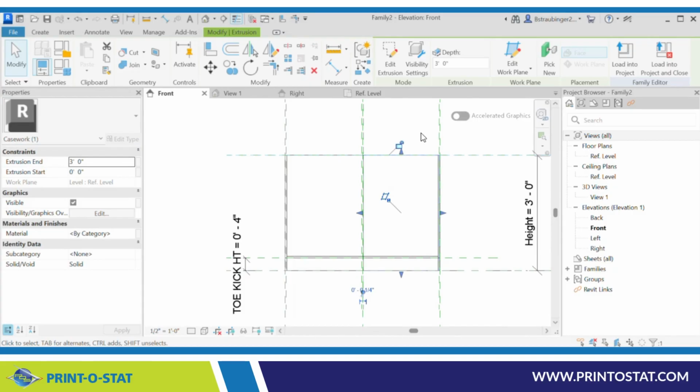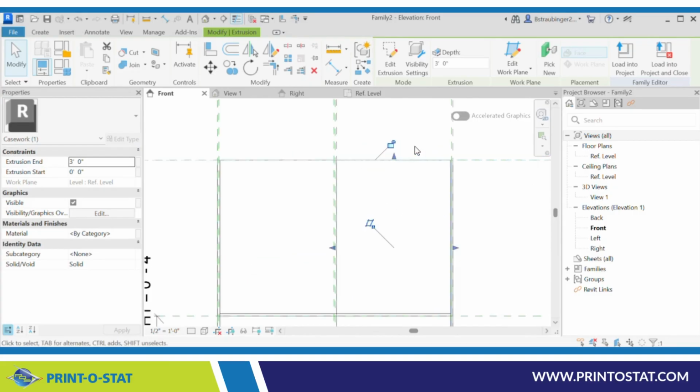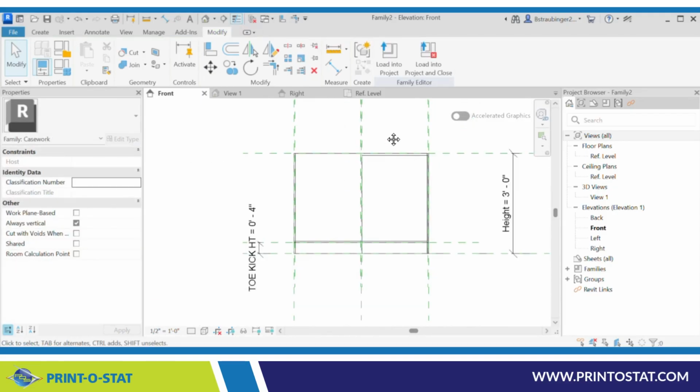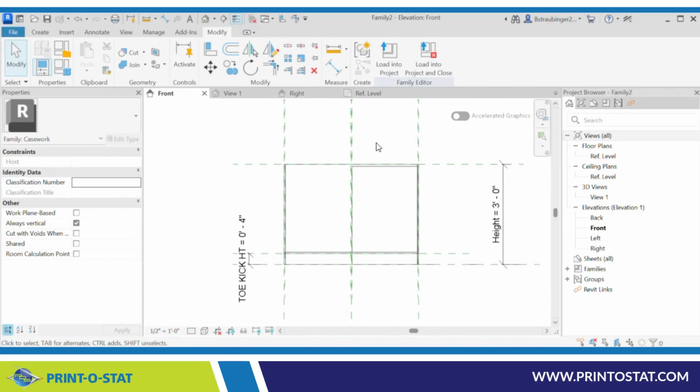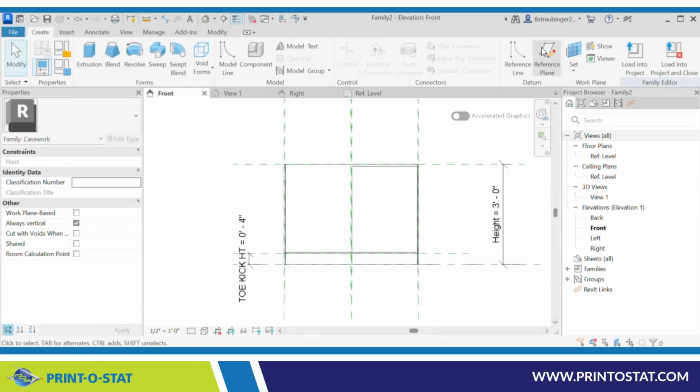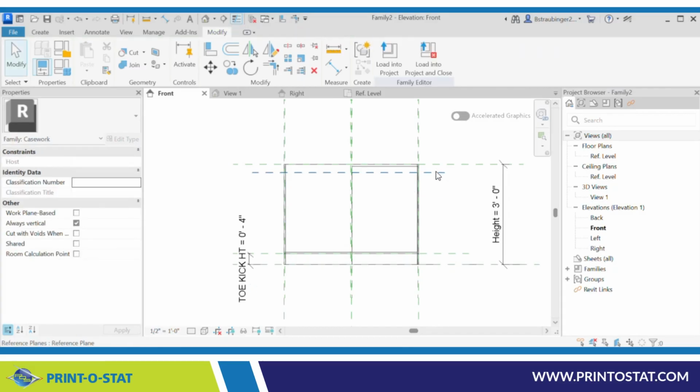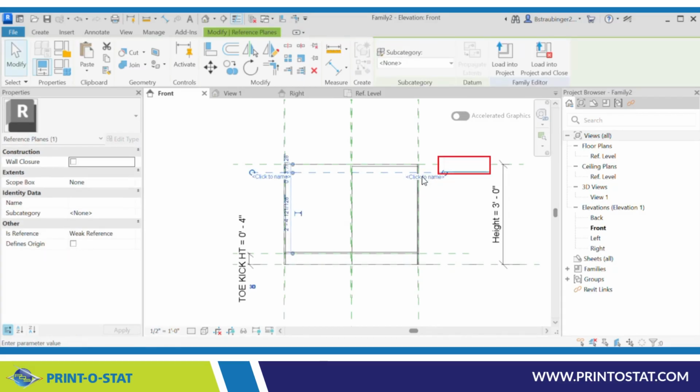And I think what I'm going to do is, because I didn't do this in elevation, now I'm going to put a reference plane in. I think I want to hold it down 1/4 inch. When I'm putting on my countertop, I don't want the door to be scraping on the bottom of the countertop. So I'm going to do create. See, I'm going to use this reference plane to my advantage. Again, this one I'll call top of door. Top of door. Just because I'm goofy that way.